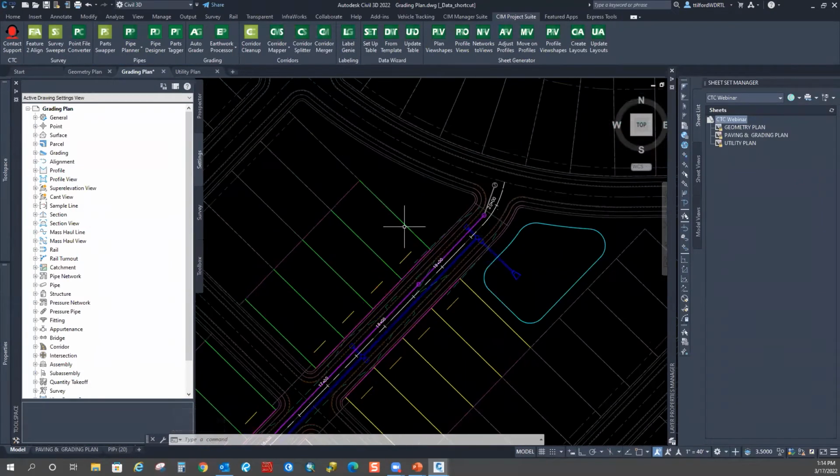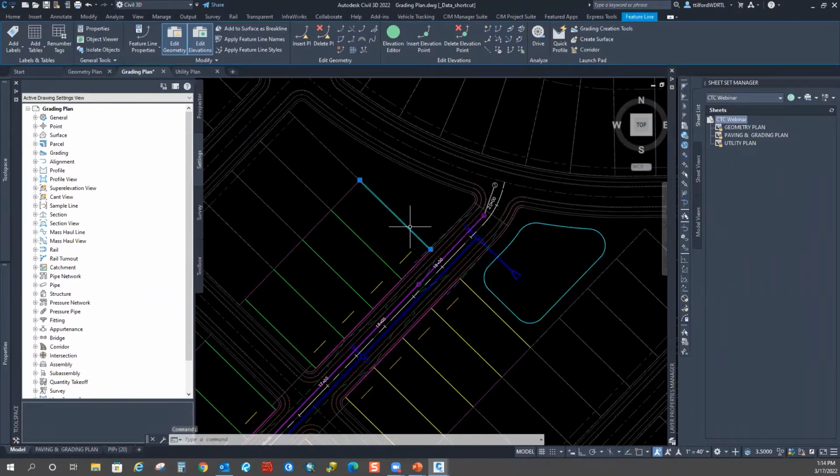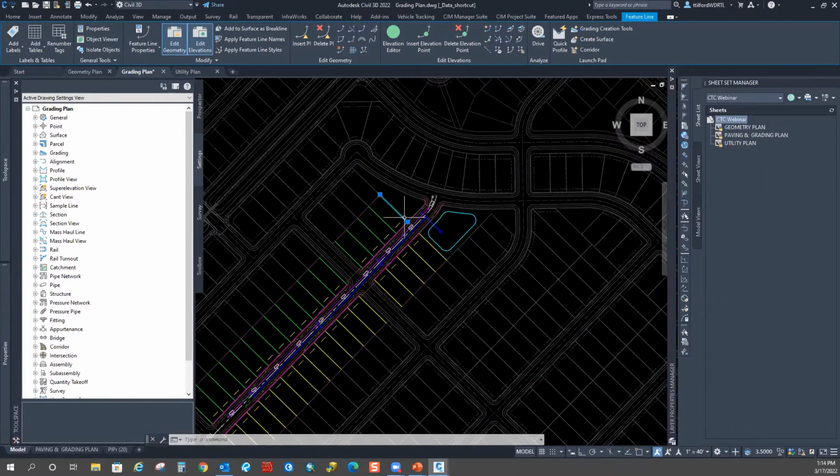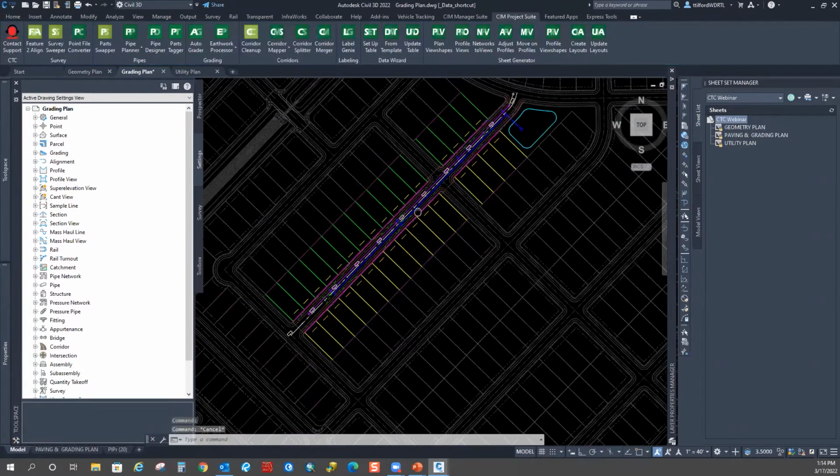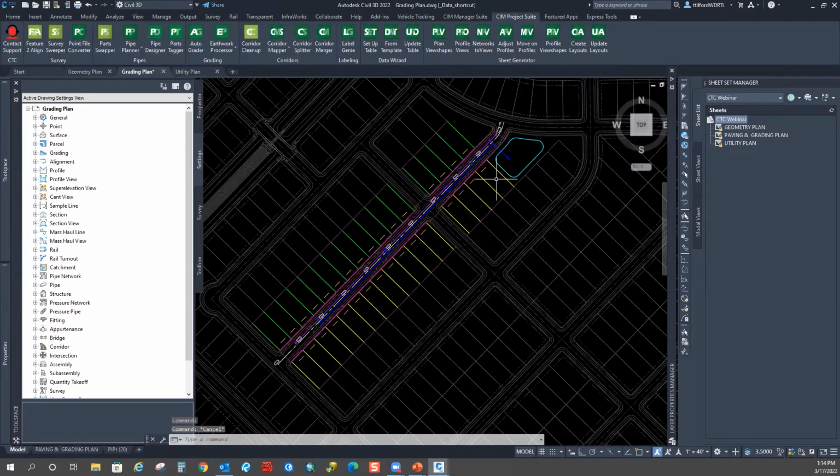The other grading over here is actually going to come and go up, I think 30 foot, back at 4%, go back at 2%, put another node, and then tie in. So it's going to actually put these nodes in here for me. And then basically what we're going to do is put some pads in here based on the A and the B lots.